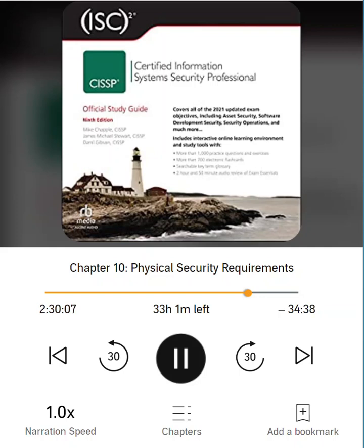Moderately secure installations work when the fence is 6 to 8 feet tall and will typically be cyclone, also known as chain link fencing, with the upper surface twisted or barbed to deter casual climbers. More secure installations usually opt for fence heights over 8 feet and often include multiple strands of barbed or razor wire strung above the chain link fabric to further deter climbers.